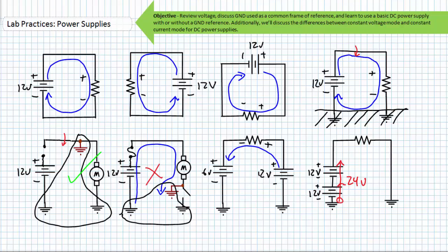If the right lead of our load resistor is hooked to ground, conventional current will travel in this direction and induce a voltage drop with the indicated polarity. This is a series aiding relationship, where one voltage source's negative terminal is simply referenced from another source's positive terminal, in effect increasing the available voltage.